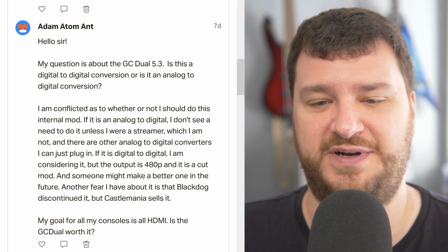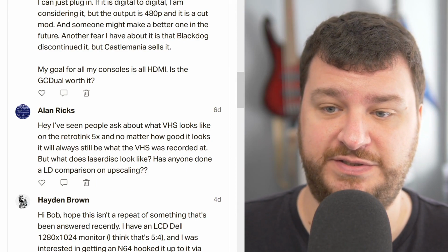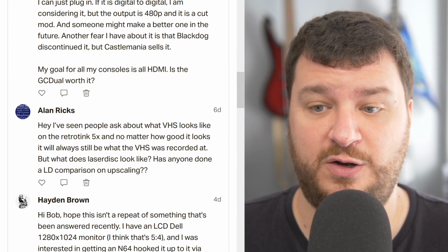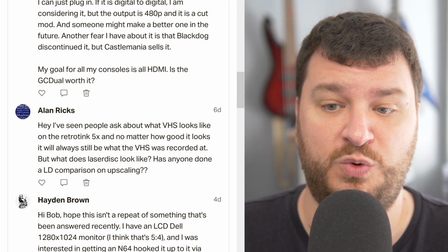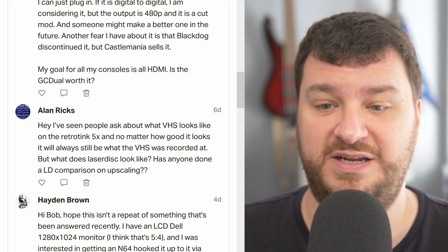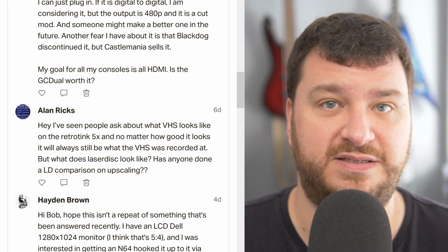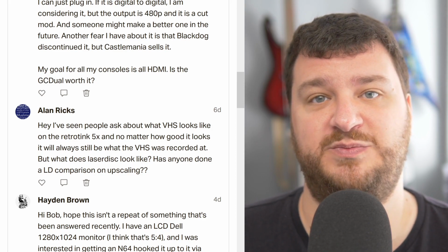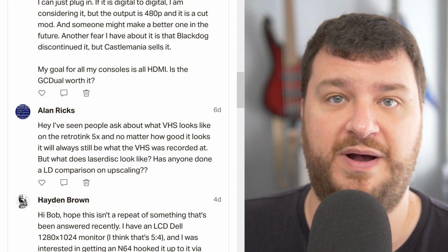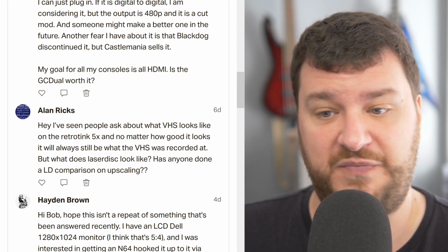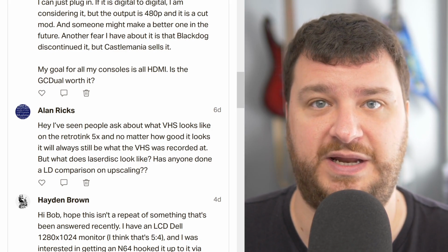Alan Rick said they've seen people ask about what VHS looks like on the RetroTink 5X, and no matter how good it looks, it'll always still be what the VHS was recorded at. But what does LaserDisc look like? Has anyone done a LaserDisc comparison on upscaling? Same exact scenario. So the best possible signal you're going to get from a LaserDisc is still a 480i composite video encoded signal. That doesn't mean it's not going to look good when you scale it. It just means you have to have realistic expectations.